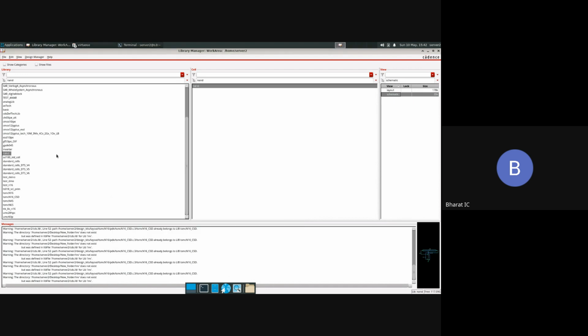For work purposes, we will be teaching on GlobalFoundries 12 nanometer, TSMC 16 nanometer, and UMC 28 nanometer in the class, and 5 nanometer will also be there. Apart from this, we have other technology nodes also, TSMC 40, TSMC 65, SCL 180. We are actually making our own LDO, so we are using SCL 180 for our fabrication purpose also.